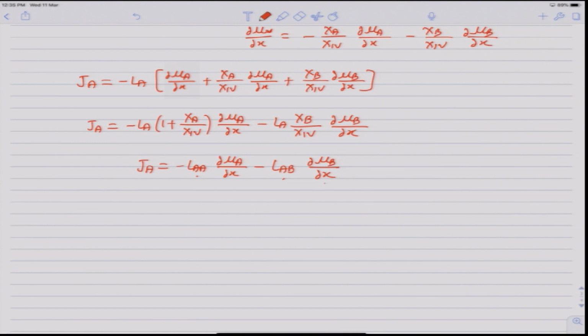This will be true whenever vacancy diffusion is involved, or whenever we are considering substitutional diffusion by the vacancy mechanism, because to more or less extent there will always be a net vacancy flow as long as dA star is not equal to dB star.